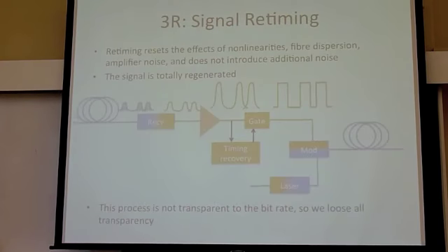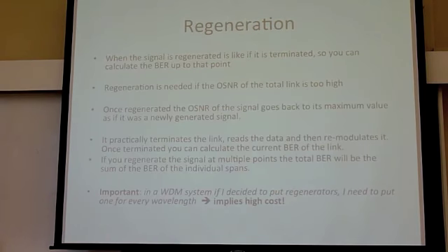How do you decide? So basically you're checking the bit error rate, but every amplifier doesn't check the bit error rate. No, this is when you do the design of the system. Okay, so you have a paper only for fixed networks. Yeah, exactly. Now there are things about dynamic networks which come with optical switches, but one of the main problems is, if you switch a signal that was going this way and now it goes this way, and maybe it goes a different distance, then how do you know if you can do it or not? That is actually a problem with dynamic networks.